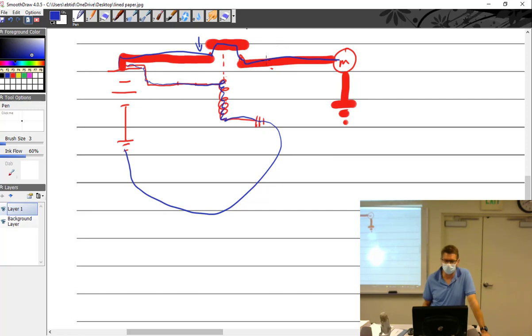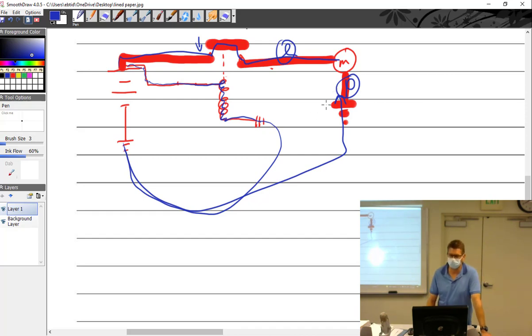Now, again, if I want to put a light over here to see when the motor's running, does that work? No. It does not work. You got to figure out another way to do it. So, all right, so, huh? Could you put it after the motor? Nope, because think about it. If I put it right here, in reality, the current's really flowing this way. And so if it's in that line, it is not going to work.